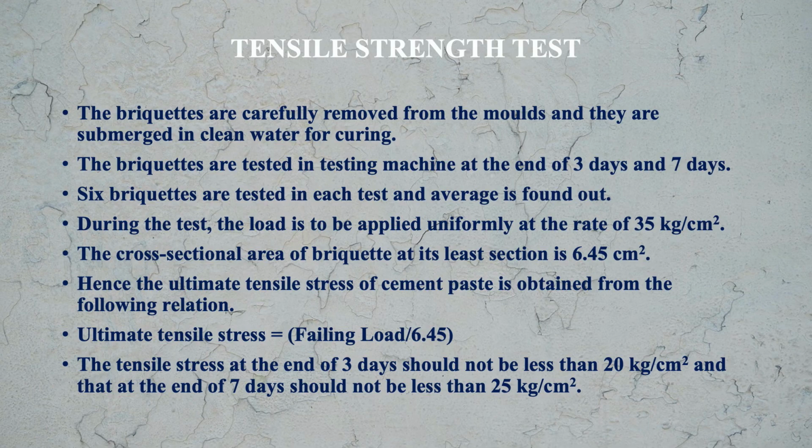Now the tensile stress at the end of 3 days should not be less than 20 kg per centimeter square, and that at the end of 7 days should not be less than 25 kg per centimeter square. So this is the way how we do the tensile test.